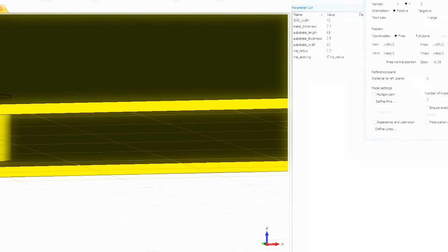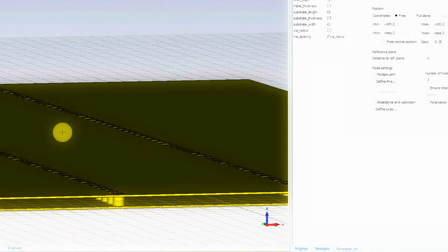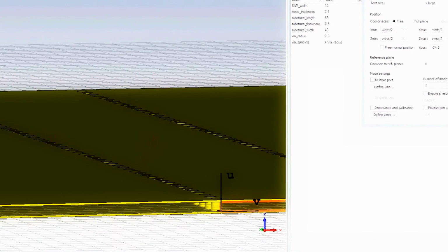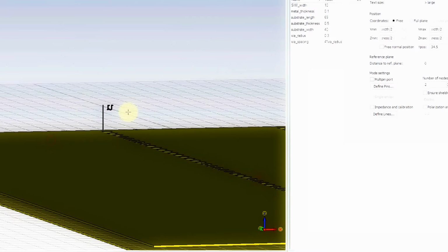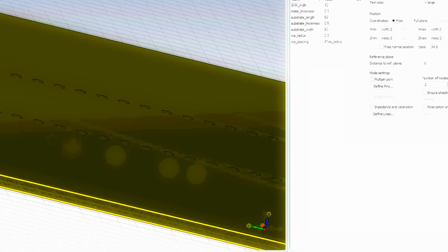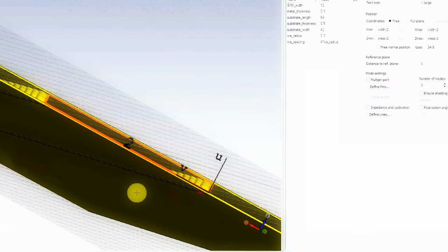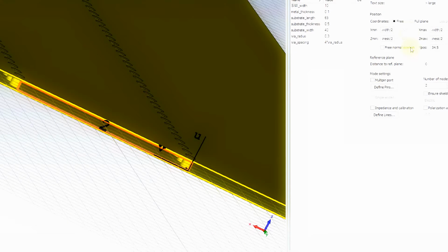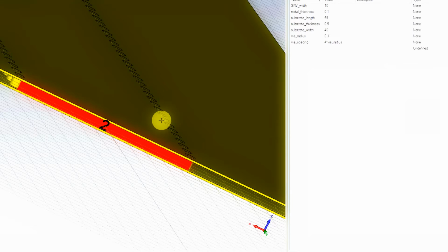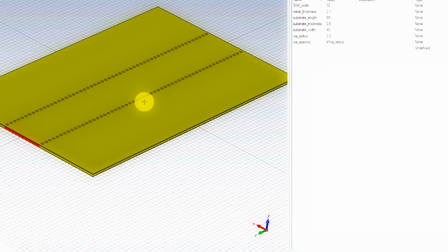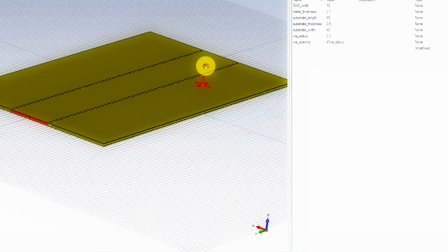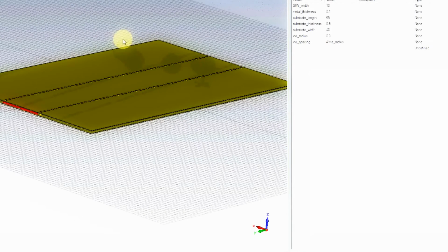Okay, click apply. Then it will go automatically to port 2. And for some reason, CST is a little bit buggy. Even though it had Y selected, it was pointing in the Z direction. Anyway, never mind, negative. So you'll see that the negative port has appeared on the other side. If I flip the model around, it already has the right sizing because it's kept it from what we did the first time. It already has two modes. So we just click OK. Right. So I think that is it as far as our model goes. Now, what I'm going to do first is here, click Setup Solver.